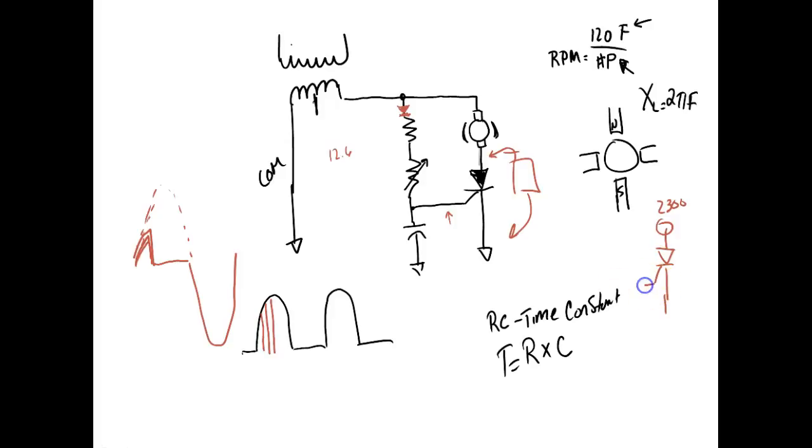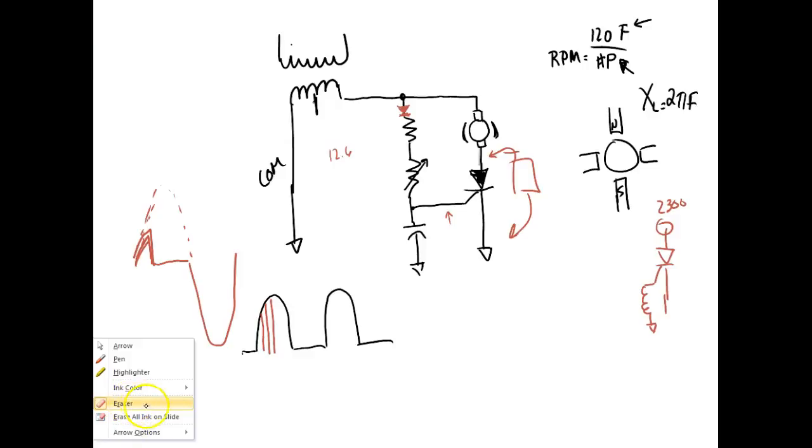So what we'll do is we'll put one of these little pulse transformers out here. And then my electronic circuit that's firing the SCR will run 2 little wires over there, one from the cathode and one from the gate. So these guys here will have multiple wires hooked on.